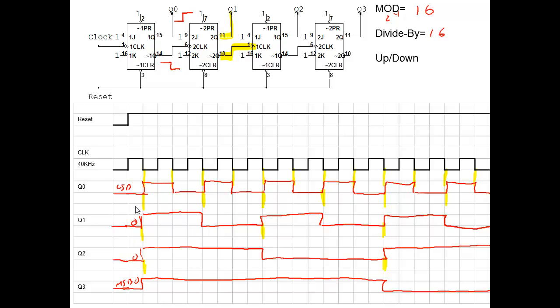So we've got 0, 0, 0, 0, 1, 1, 1, 1, 1, 1, 1, 0, and 1, 1, 0, 1. So here we have a 0. Now we've got a 15, 14, 13. Well, now what does it look like it's doing? Well, it sure looks like it's counting down to me. It's going lower as we go across. So this is how you make a down counter out of negative edge triggered flip-flops, as you do it by doing the inverse of them.